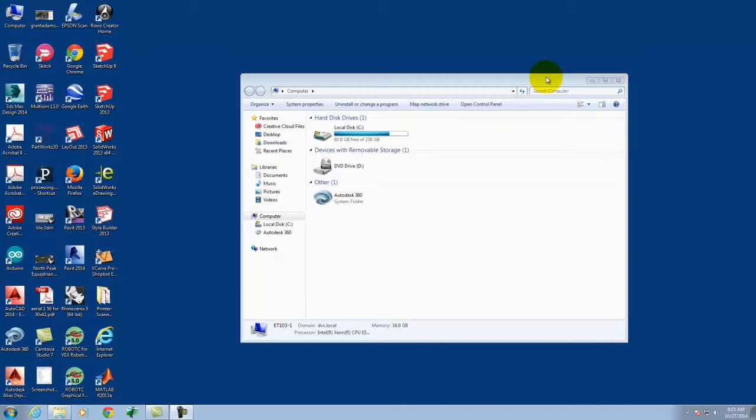And that's one of the biggest shifts that happens when you start working in a true drafting program like AutoCAD, in that everything is actually full to size. So we're not going to scale anything in our heads. If we're drawing a building that's 10 feet by 20 feet, when we draw it in AutoCAD, it's going to be 10 feet by 20 feet. So everything's full scale. The scaling to make it into a drawing size comes later. And so that's something that's very important to understand.